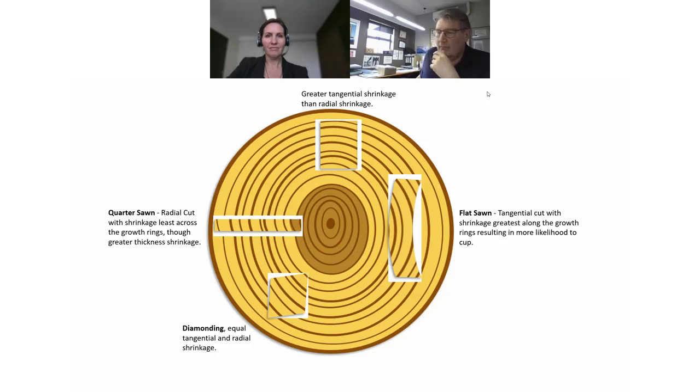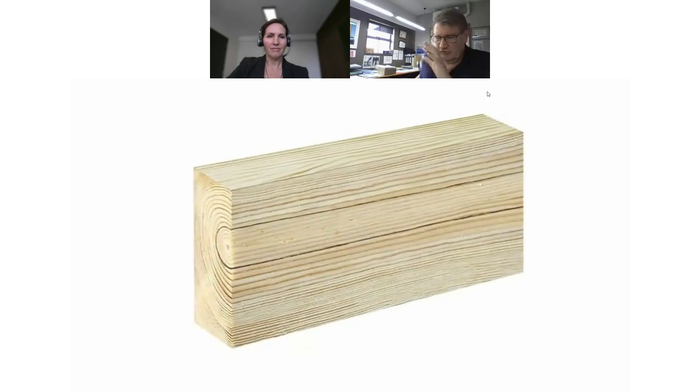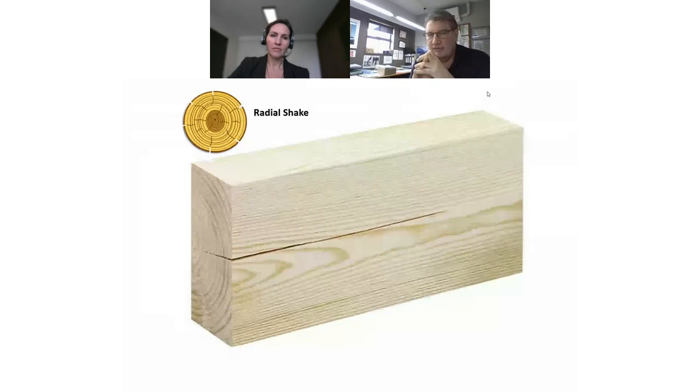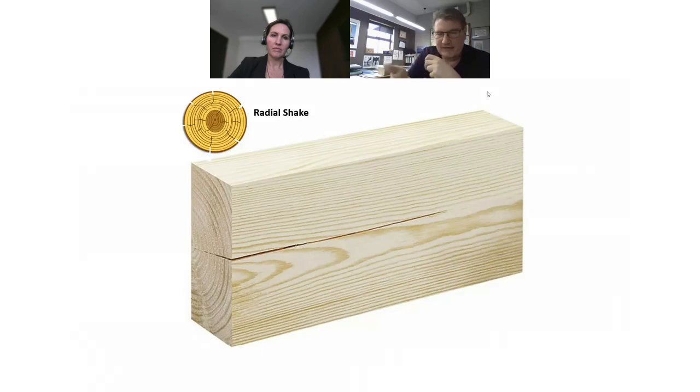So I've just thrown these in because you shouldn't see these, but when you're in the timber industry chopping up logs, you hear things called shakes, and it's a stress and a crack within the log itself. This is little cup shakes. If you've ever seen that before, it's interesting. Here's one for you, a radial shake, and it's to do with stresses on the log when they chop them down and they smash into other things. It can cause stresses, and also from drying unevenly and all these sorts of things. And you see that split there.